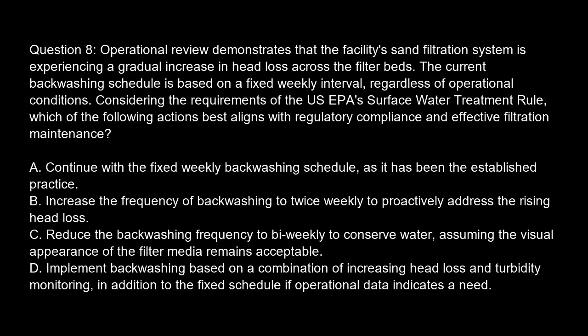Option A. Continue with the fixed weekly backwashing schedule, as it has been the established practice. Option B. Increase the frequency of backwashing to twice weekly to proactively address the rising head loss. Option C. Reduce the backwashing frequency to bi-weekly to conserve water, assuming the visual appearance of the filter media remains acceptable. Option D. Implement backwashing based on a combination of increasing head loss and turbidity monitoring, in addition to the fixed schedule, if operational data indicates a need.